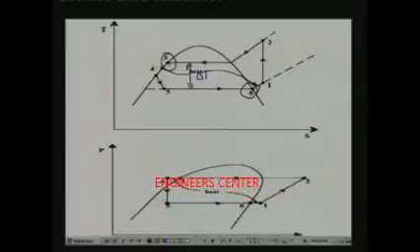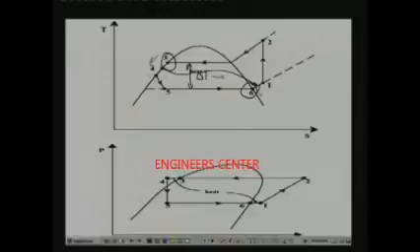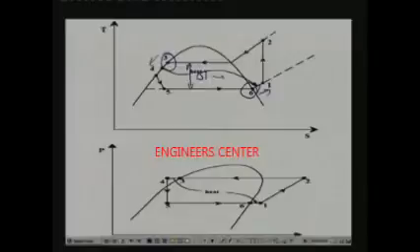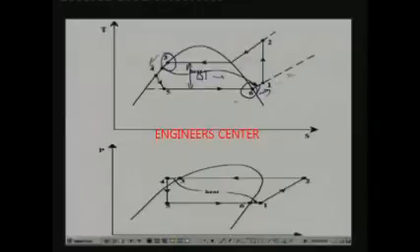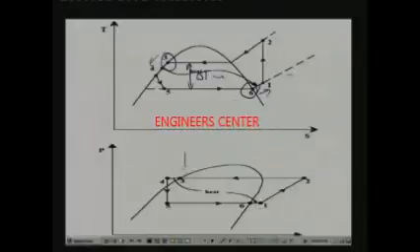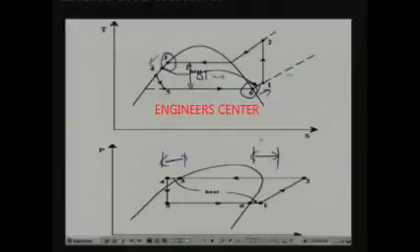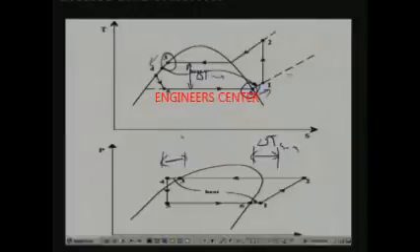So this is exchanging heat like this, this is the arrow. In this process this temperature is reducing and this temperature is increasing, and both the processes are typically almost isobaric. So subcooling takes place along the constant condenser pressure line, and superheating is taking place along the constant evaporator pressure line. The same thing is shown here also. So you can see that this is your process of subcooling and this is the process of superheating. This is delta T superheat, and this is your subcooling.